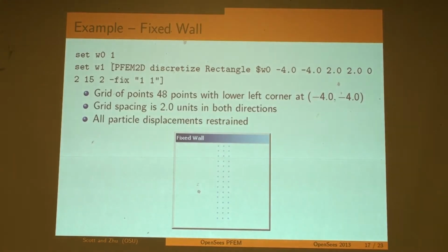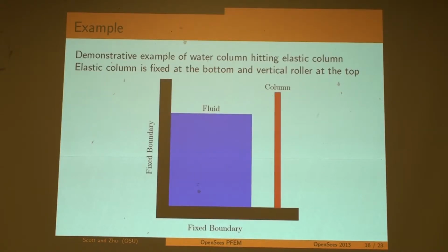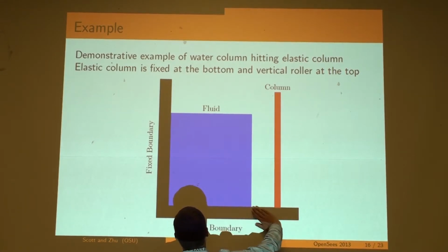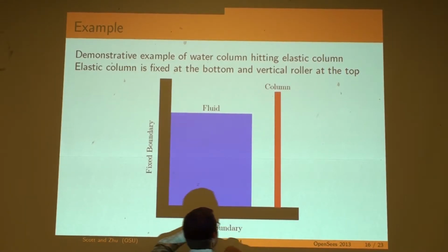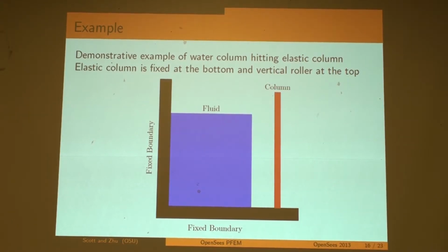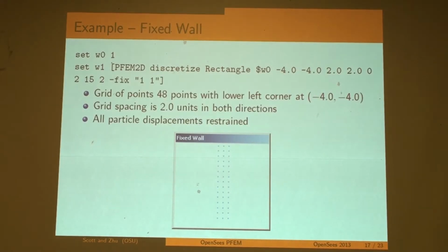Okay, so first we just go through and we can use the discretize rectangle command to create this rectangle, this rectangle, this rectangle, right, and then create a bunch of beam elements along the height of that structural column to do our analysis. Okay.